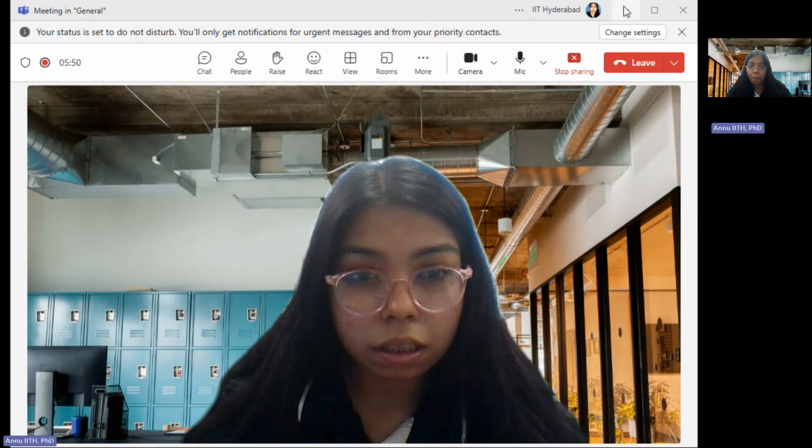So Z transform properties 2 is conjugation and convolution, which is the focus of conjugate symmetry, and convolution in time leads to multiplication in the Z domain. So this is the conjugate property. What does that mean? The Z transform of x of n is equal to X of z. So if the conjugate is taken, it leads to X star of 1 upon z conjugate, where the star denotes complex conjugation.